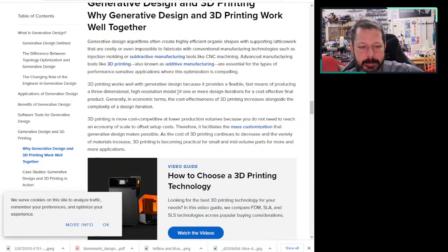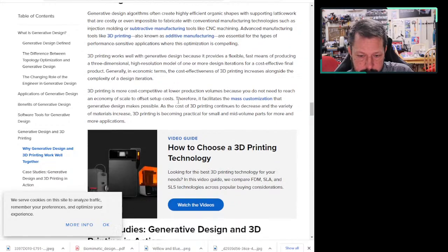Now, this is Formlabs. They have a consumer-ish level, at least small industry level, laser-based resin printing, small desktop printer as their main product. You can get their smaller ones in the $4,000 range, I believe. So this does kind of apply to them. But you are doing resin printing. It's not laser sintering. It is laser, but it's laser polymerization, not sintering.